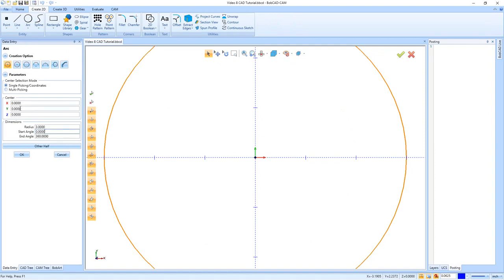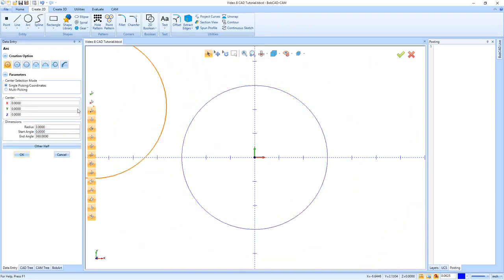We're going to center it right there on XYZ 0. From here we can hit OK, and there's our first arc on the screen. Now I'm going to change the size of this to 0.1875, 3/16. Then I'm going to take my X and set it to -2.5. Then just click in another box or again hit Tab, and then hit OK. Then I'll make another one that goes to X 2.5. Now we have 2 holes on both sides, so we'll hit OK there.